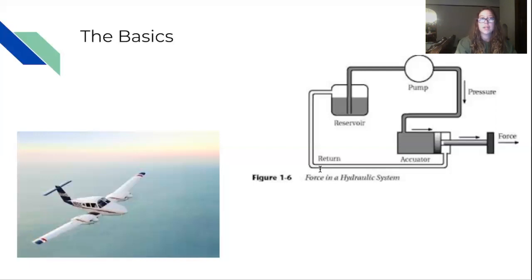The actuators are what give the hydraulic system its power, and there are a few different types of actuators. One is the single acting actuator, which allows pressure from the hydraulic system to only be applied in one direction. And for it to be moved back into position, it's going to need a different mechanism, such as a spring. Another option would be the double acting actuator. This allows the hydraulic system to move it in two different directions because it's able to apply pressure from both sides.